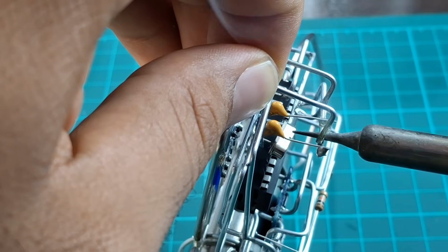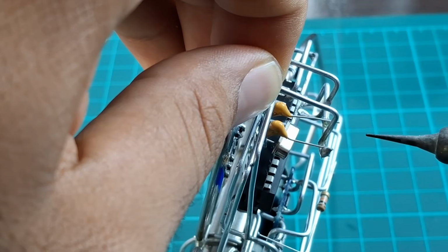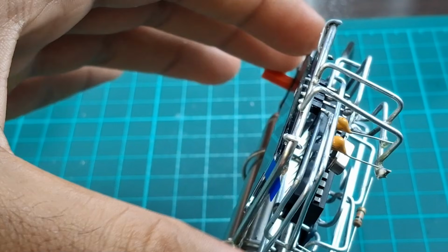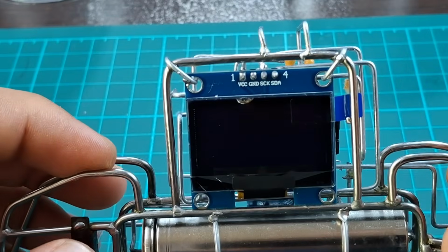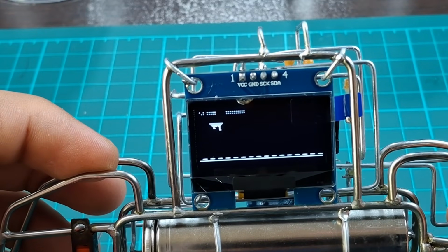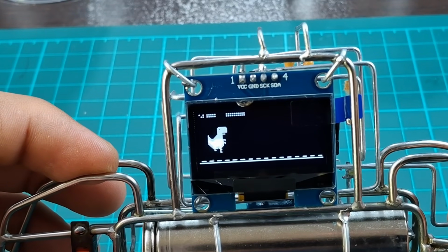So I thought let's connect those pins to the ground again. But that wasn't actually the problem. This was. If you remember, when I was soldering the VCC connection, I made the mistake of leaving no space between these two wires. They were touching each other, causing the display to freeze. But when I accidentally soldered the ground connection, these two wires got separated, and suddenly the whole thing started working.